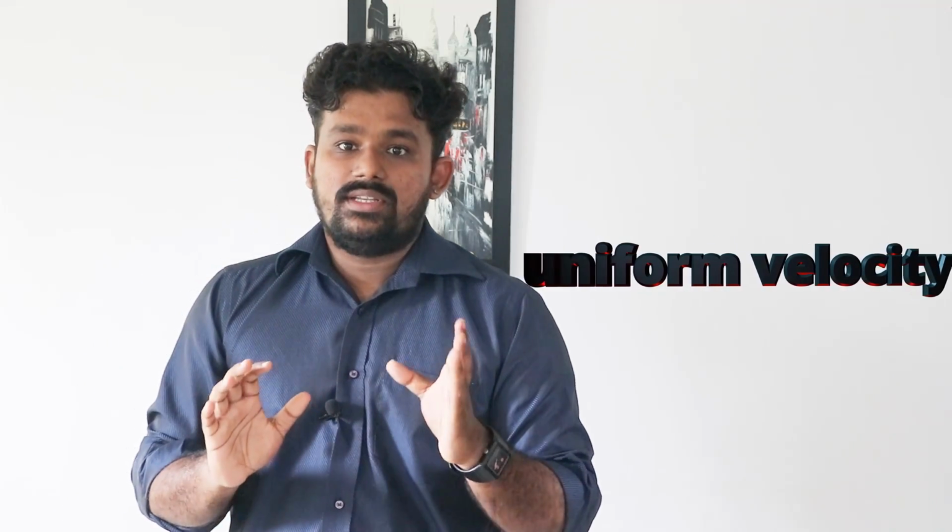Third, the flow should be along a streamline. Bernoulli's equation applies along a streamline, not across flow. Fourth, the velocity should be uniform, which is the fourth assumption taken.